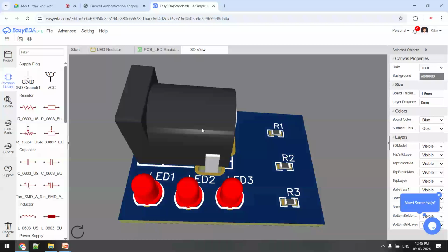Optimize means I don't want to use this much area. Okay, half area is sufficient, or one third area is also sufficient. How? By which way it is possible? Some components below on second layer. Because one plate we have already occupied, so why not optimize? So for example, few LEDs and resistors I want to place at the bottom, and DC supply at top, that we can do.